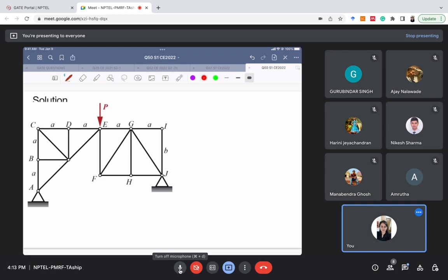So we will write the joint name first, the number of forces in x direction, and the number of forces in y direction. We can choose a joint which has a maximum of 3 connected members, not more than that.